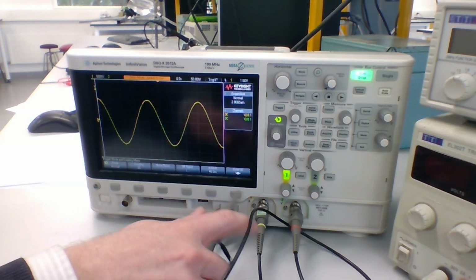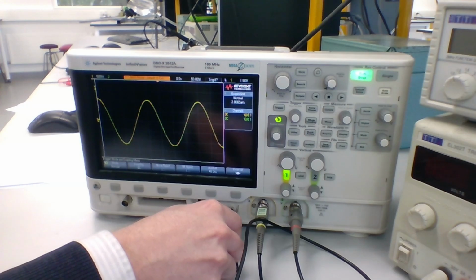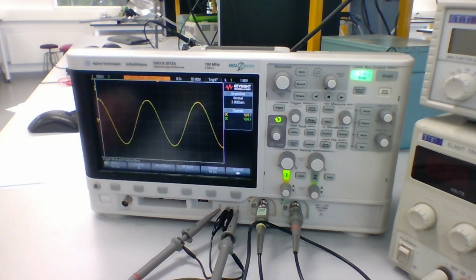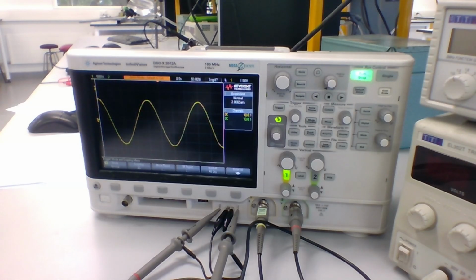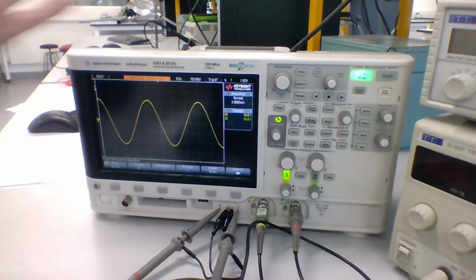Now, if I reconnect the probe back to the Demo 1 hook, you can see still nothing changes. Again, we're still using this normal triggering mode. No waveform has gone across the trigger threshold in the way we've specified. Remember, we have this set to a falling edge at 1.5 volts. So no waveform on channel 1 has gone from above 1.5 volts down to below 1.5 volts. So nothing has occurred to make the trigger take a capture or take a measurement. So in normal trigger mode, nothing will happen.